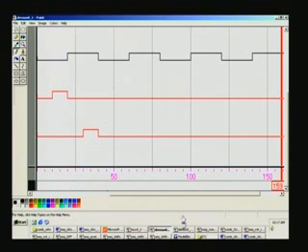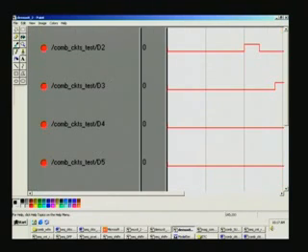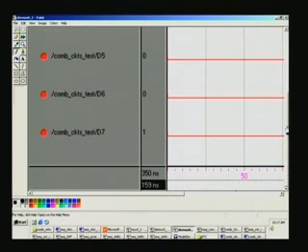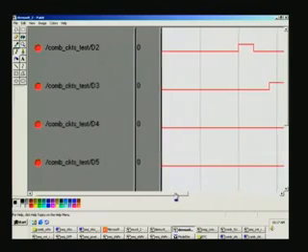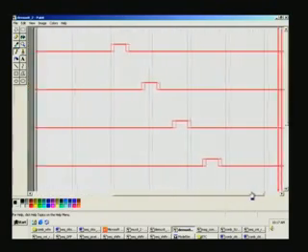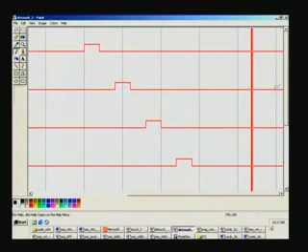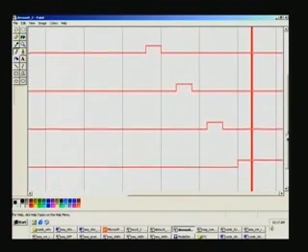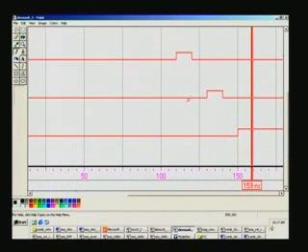And so then we move on to these other outputs in the waveform in this file. We had seen D0 and D1 there, and D first at this position and this position. Now in the third position you have D2 here, and you can see the time base is also the same, 50. So D2, D3, D4, D5, you can clearly see all of them going on by one clock period as such. In fact, being combinational, there's no clock period. It's every 20 nanoseconds that's happening. So the final output you see remains at 1 as such.